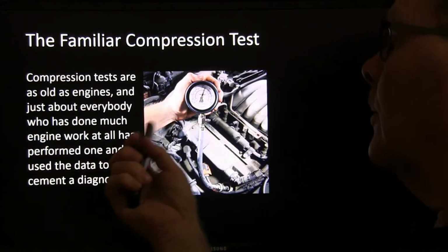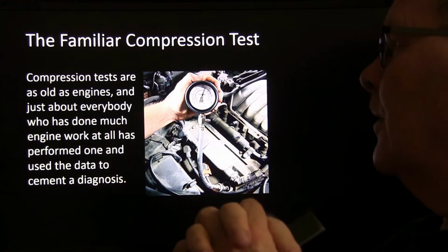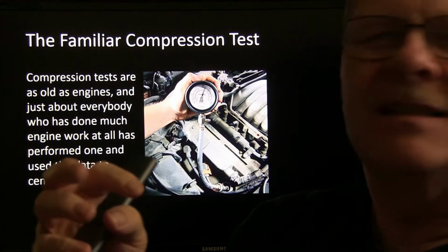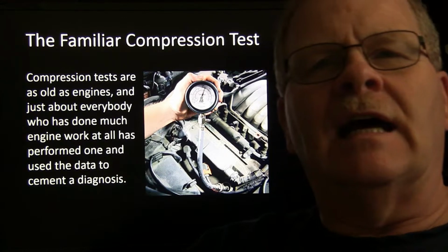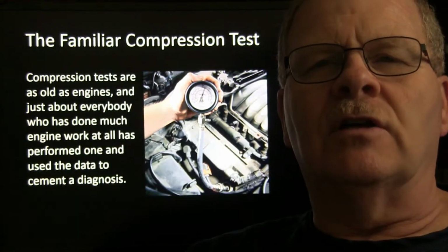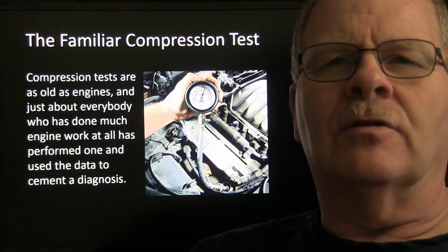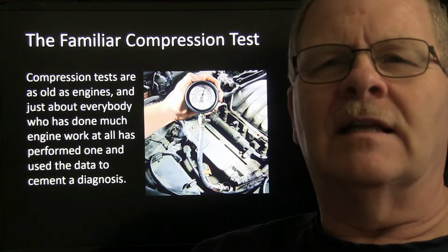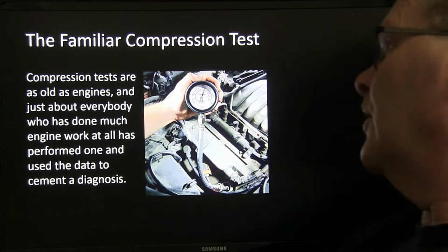Well, compression tests are about as old as engines, and just about everybody that's ever done engine work has performed one and used the data to submit a diagnosis. You can get an idea of what this engine's doing, as far as how each cylinder is breathing, by the way that you measure the compression. There are some numbers that vary on that, but they say the lowest shouldn't be any less than 70% of the highest whenever you're doing compression.